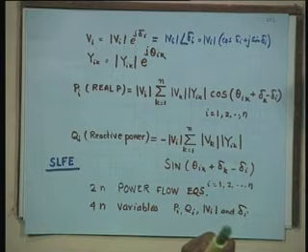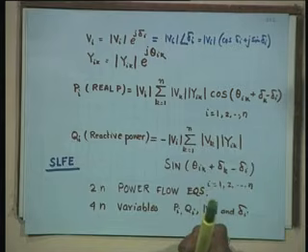Please remember, these thetas will be close to 90 degrees, because resistances or conductances, as the case may be, are always negligible in power systems. If they are not, then such a power system is called an ill conditioned power system, which I already told you last time. And we do have ill conditioned power systems at times, and at that time you can't ignore resistance or conductance.